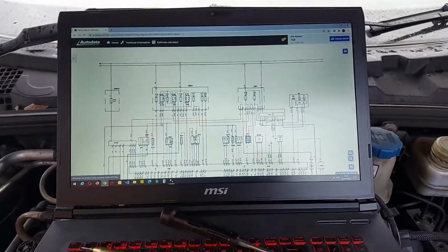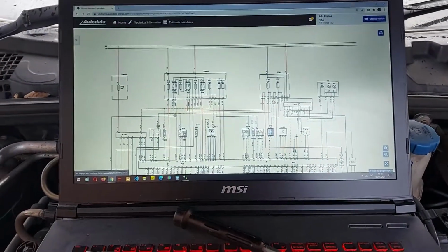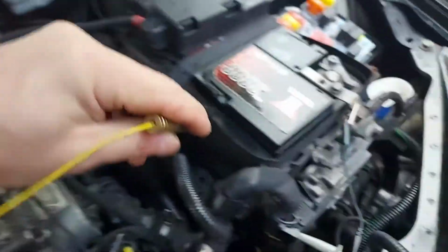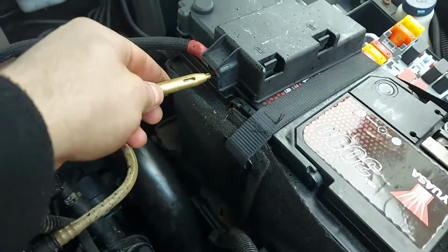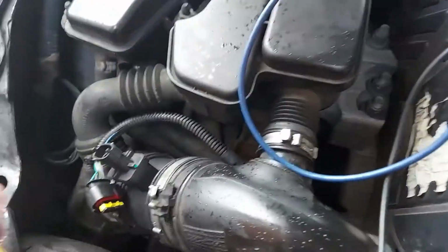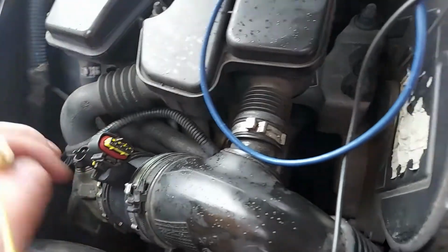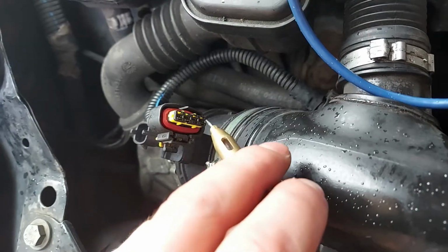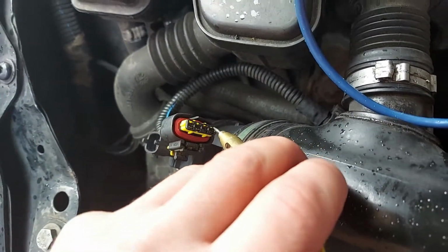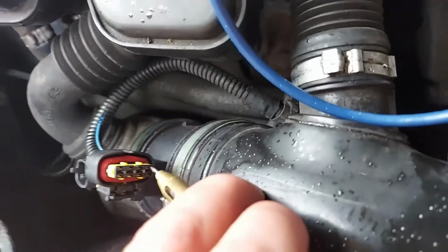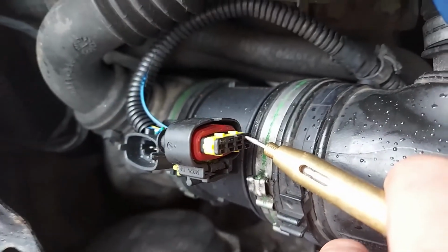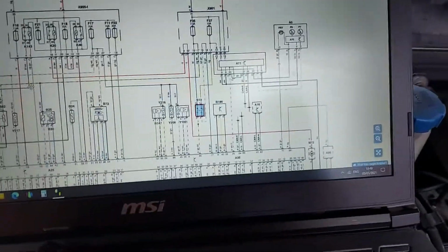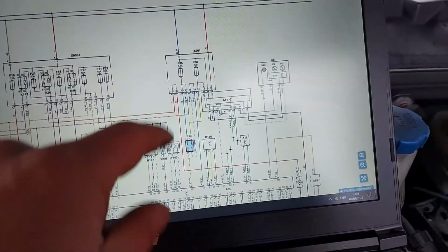So okay, let's put ignition on. Okay, so we've got ignition on now. Let me take my probe. Let's see first if it actually works, this probe. Yeah, that's working. And let's gently, just barely touch the pin, but not where the pin goes, just on top here. And let's see. We've got no light. So we either have a breakage in this wire, or the fuse is gone.